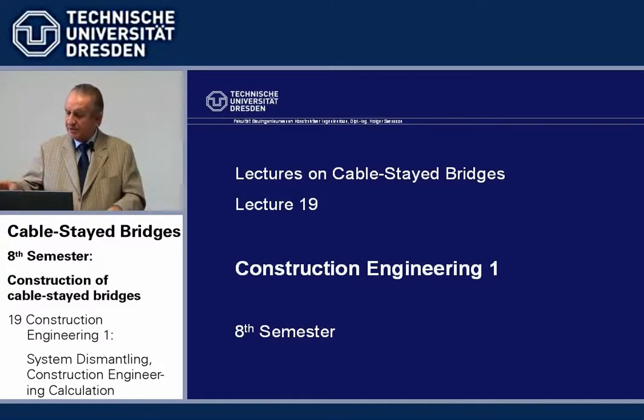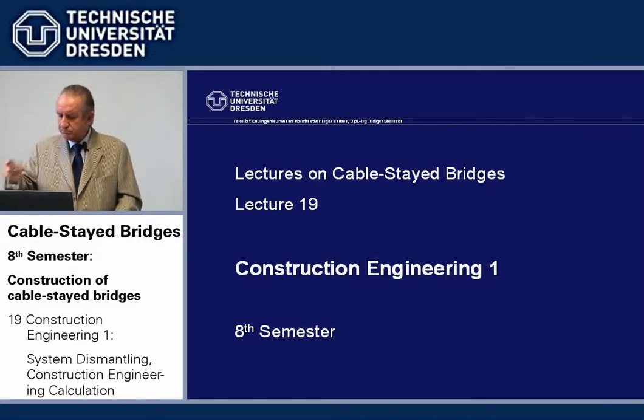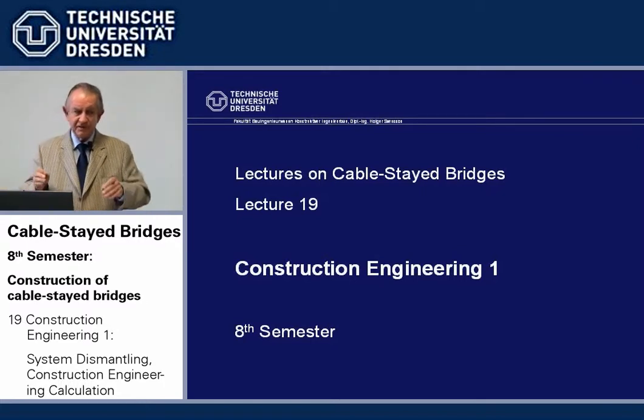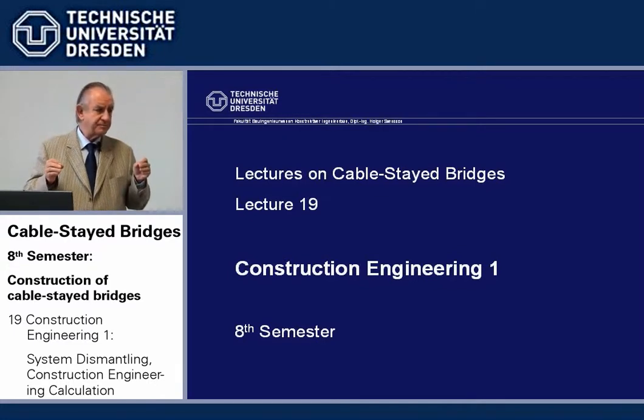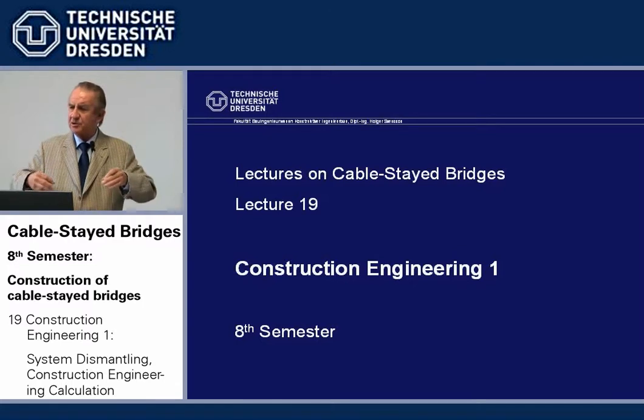The only thing we really know when we start construction engineering for a cable-stayed bridge is the final stage after shrinkage and creep. That's what we have calculated. That was the way we have sized cables and so on.